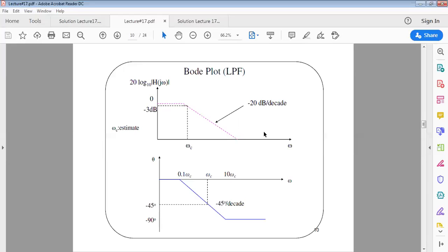The cutoff frequency can be obtained by projecting the amplitude which is 3 dB lower than the passband amplitude, and then we can read off the frequency. For instance, if your amplitude plot is at 0 dB, then 3 dB lower will be the location of your cutoff frequency.